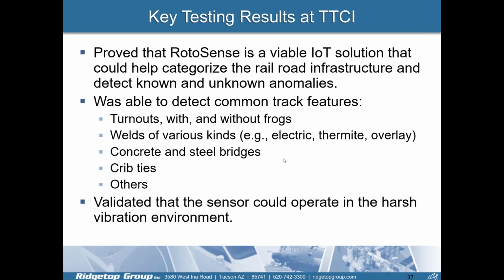When you look at some of the IEC specifications for this infrastructure, they have a Category 1, which I think is vehicle mounted, Category 2, which is bogie mounted, and then Category 3, which is where the wheel mounted version is. Each of those has very specific vibration or testing requirements, and we're able to operate in that harsh operating environment.